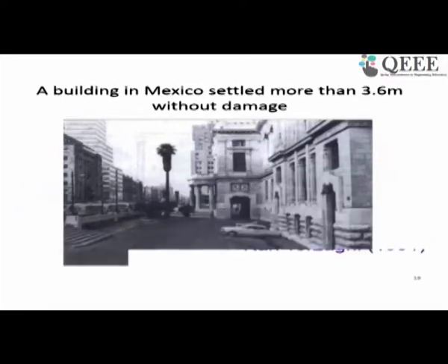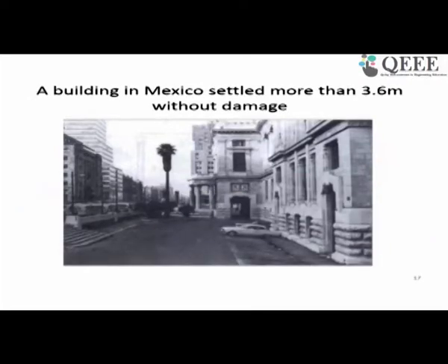These are some particular cases where a specific investigation is needed before you actually go ahead with the structure design, whether it is sensitive clay or expansive clay, or a lot of settlement may happen, or the capacity is very low, or it may be a liquefiable ground. We need to investigate the ground before we actually go ahead with the design.